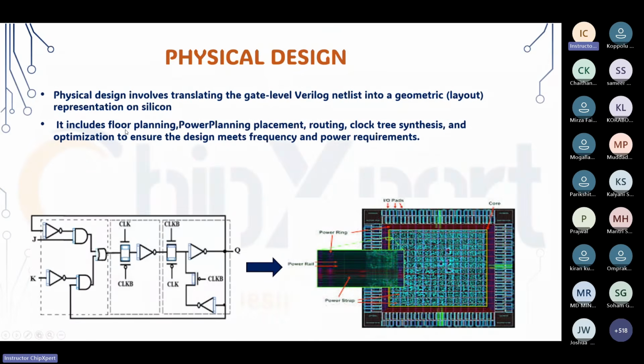The physical design process involves converting the gate level Verilog netlist into layout format by combining this analog layout and the logic. Combining the design of that Verilog file and this analog circuit together, they'll create an actual netlist where the technology mapping will happen.